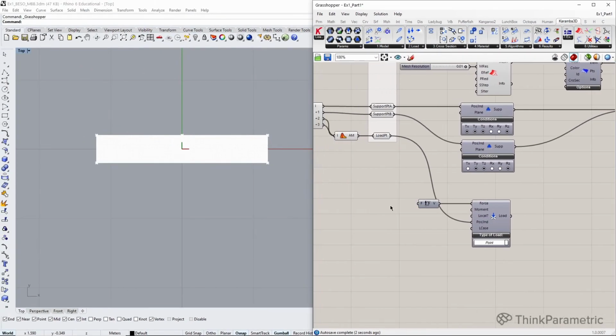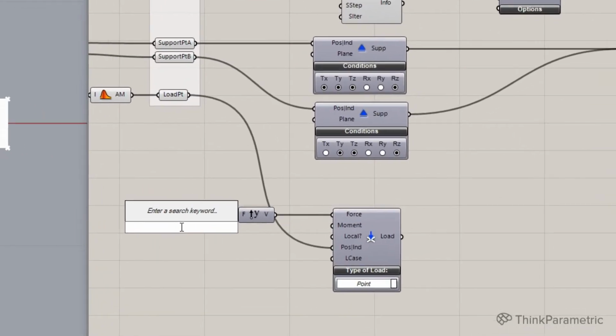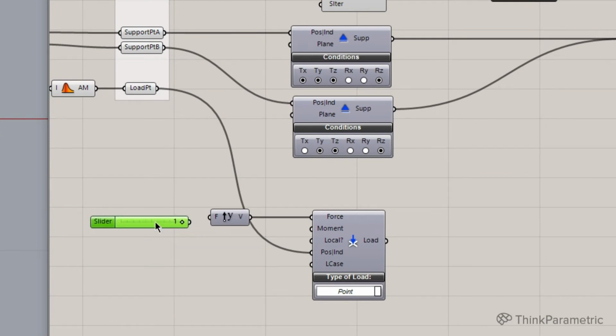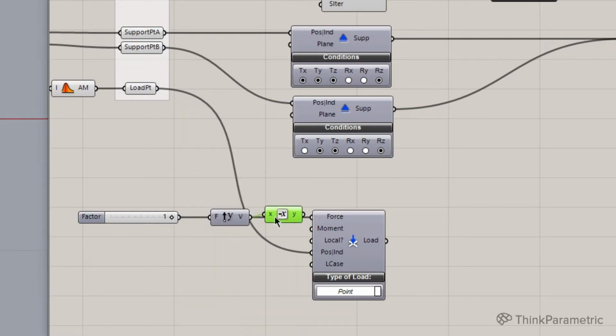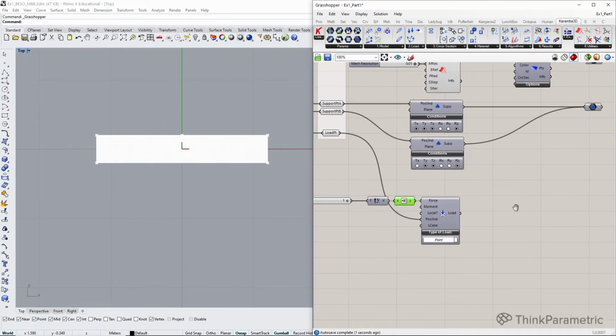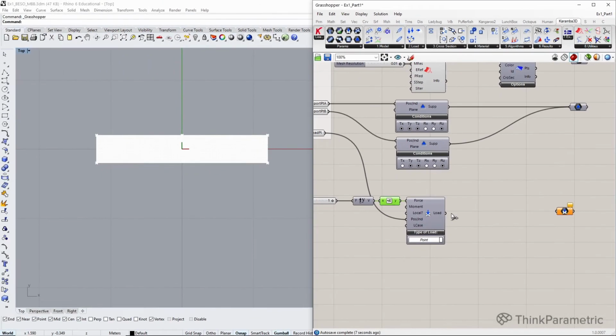And this force in our example I showed you in the presentation was of magnitude 100 newtons. Force in Karamba is specified in kilonewtons, so when we multiply 100 newtons by 10, because this is how we enlarge our design, it's 1000 newtons, so this results in exactly 1 kilonewton. Don't forget that our force should go in the negative direction. So I will just plug this negative between Y and force. And also again at the end let's create a load param.